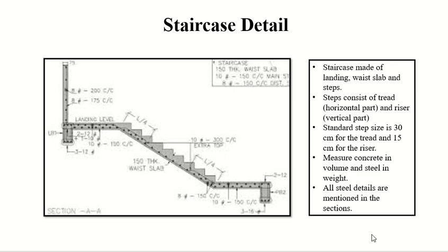And then we have the staircase as well. Somebody mentioned it in one of the previous lectures, when I was asking about something related to finishing. So staircase is not finishing. It's the actual structure, the main structure. You can see it has a reinforced wall. It has a slab, what we call the waist slab. This is what we call the landing slab. We have the landing slab here and here. Two slabs, one at the start, one at the end.